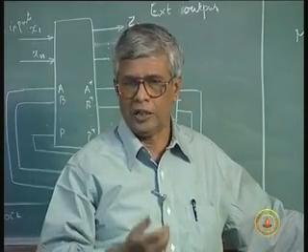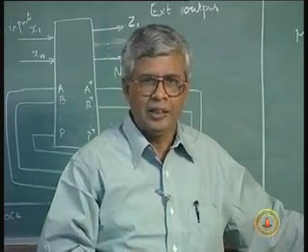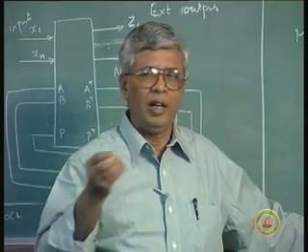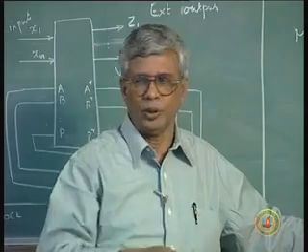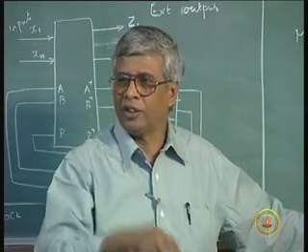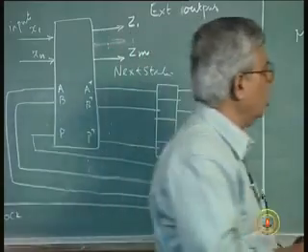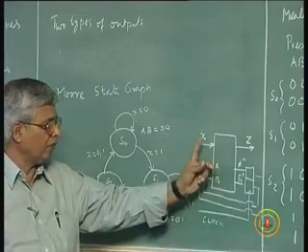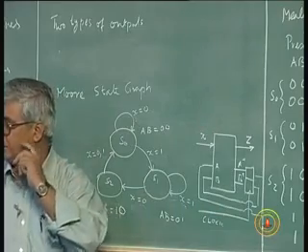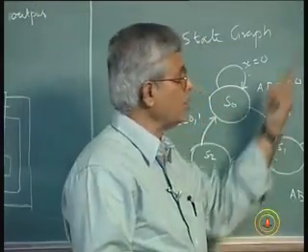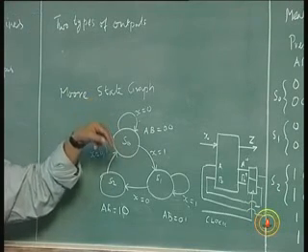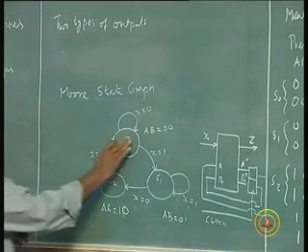Of course, when I say the output is dependent on the state variables, the values of the state variables decide the output. But you have to define it in the graph for each state. So since I have a model of X as the input and Z as the output, Z has to be shown separately in the state graph as well as in the state table, but instead of showing it along with the arrows of the inputs, we will draw it inside the circles.